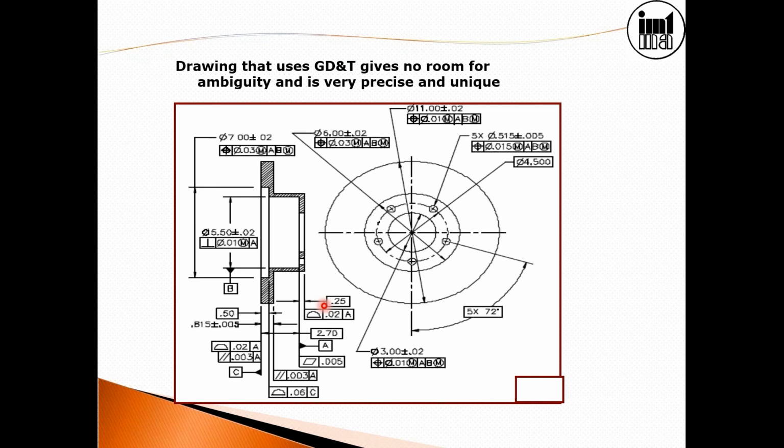If you understand GD&T completely, if you understand how to interpret the GD&T completely, you will understand why I'm making this statement. Hence, when GD&T information is on the drawing sheet, you should be able to interpret it correctly, so that you'll understand the position tolerance is not 0.3, it is much more than 0.3. We think that it is 0.3, but it is much more than that. For that, we should have the interpretation of the GD&T language.